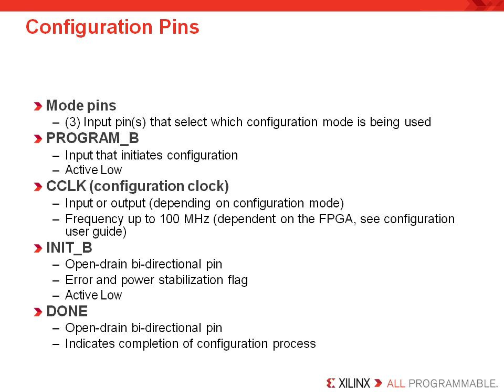The init pin has multiple functions. At the start of configuration, init goes low, signaling that the FPGA's memory is being cleared. After clearing, it is released to be pulled high by an external resistor. Later, when the FPGA is loading its bitstream, init can go low, indicating that the bitstream has failed its CRC check, and the configuration is being aborted. The CRC check is a checksum that indicates whether the bitstream has been corrupted.